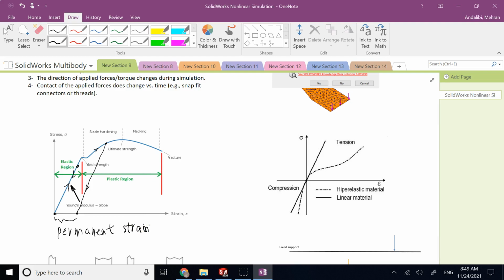There are some materials that, as I said, are nonlinear, so the behavior between the stress and the strain is not following a line, yet they are still elastic. For example, hyperelastic materials like rubber. By the way, I think this should be Y instead of I. If you look at the stress-strain relation for a hyperelastic material like rubber, the relation barely looks linear. Mostly, it's entirely nonlinear.